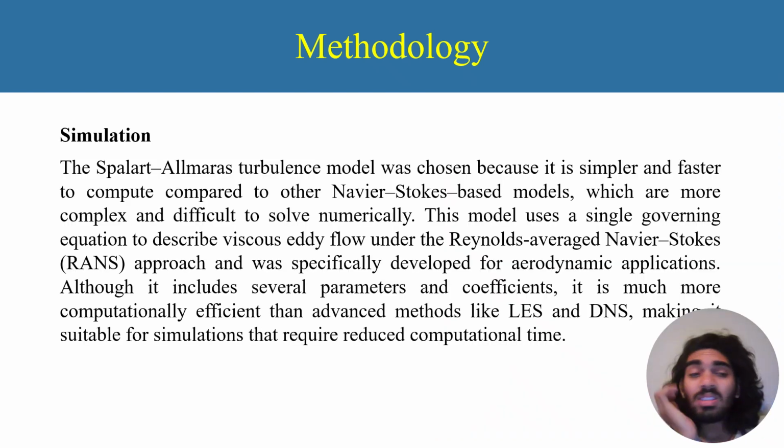For the simulation, based on the referred paper, I am going to consider the Spalart-Allmaras turbulence model, and I am going to use the RANS model. Why? Because for this aerodynamic application, RANS is good in comparison with LES and DNS, which take much more computational time, but the results were much similar. For me, this simulation took 2 weeks. If I used LES or DNS, it would take about 1 month.